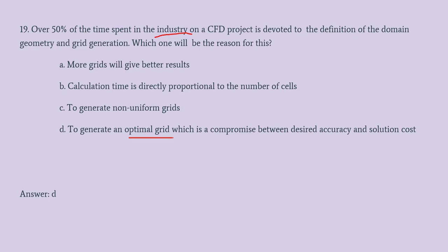We shall be defining the shape of the grid which we are using, say triangular mesh or square mesh, and then we alter the dimension of that mesh, and thereby we see how many meshes are fitting inside the geometry. Okay. Then again, if we have to split the entire CFD process into two, the large chunk or the equal chunk will be grid generation, or geometry specific thing.